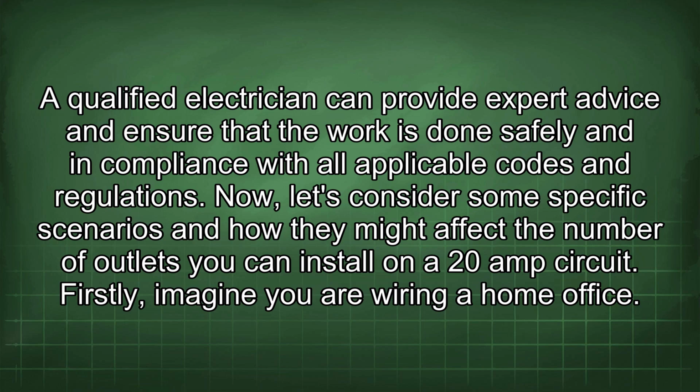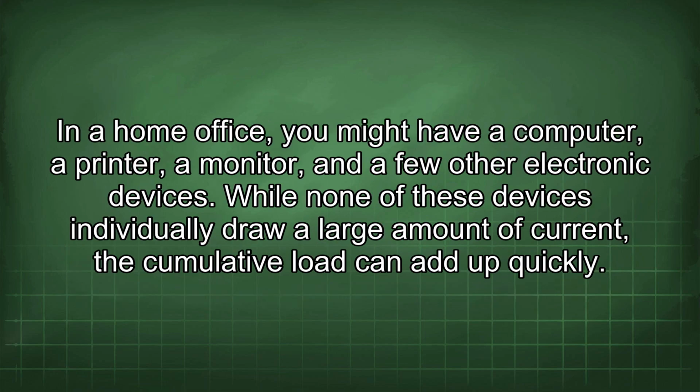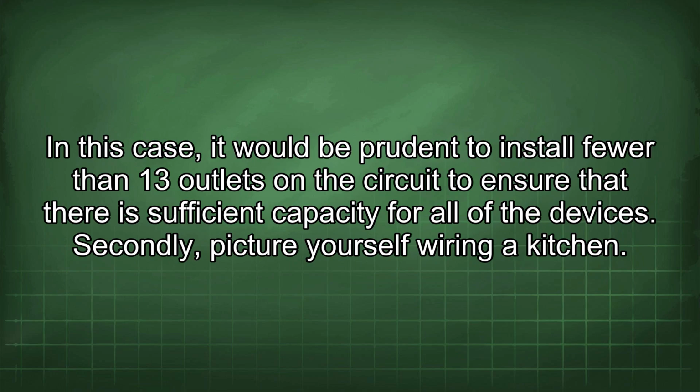Now, let's consider some specific scenarios and how they might affect the number of outlets you can install on a 20 amp circuit. Firstly, imagine you are wiring a home office. In a home office, you might have a computer, a printer, a monitor, and a few other electronic devices. While none of these devices individually draw a large amount of current, the cumulative load can add up quickly. In this case, it would be prudent to install fewer than 13 outlets in the circuit to ensure that there is sufficient capacity for all of the devices.